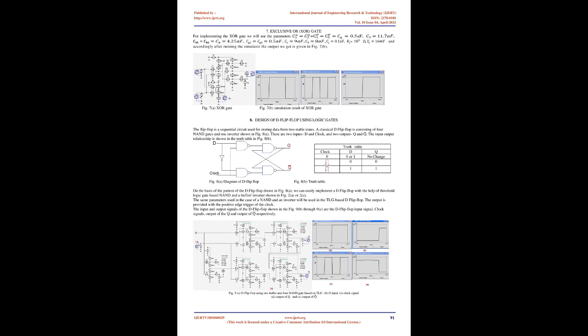In this work we assume the Boolean logic inputs correspond to voltages like logic 0 equals 0 volts and logic 1 equals 0.1 times e/C. We assume, for simulation and other purposes, C equals 1 aF; then logic 1 equals 0.1 times 1.602 times 10 to the power of minus 19 over 10 to the power of minus 18, equals 0.1 times 1.602 times 10 to the power of minus 1, equals 16.02 times 10 to the power of minus 3, equals 16.02 mV, about 16 mV.